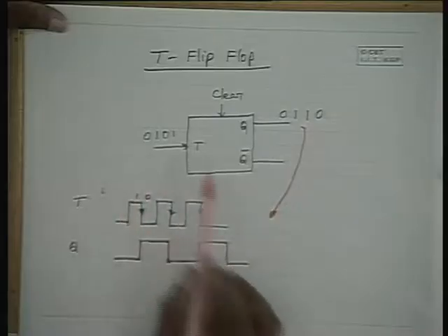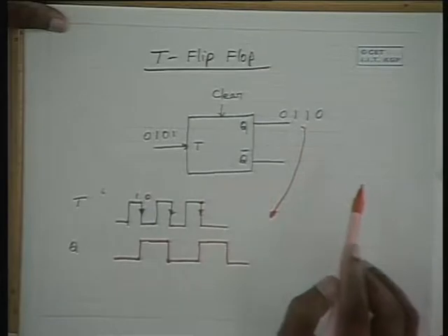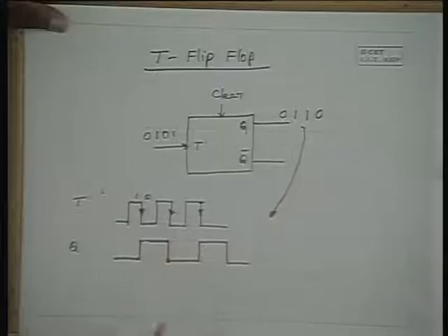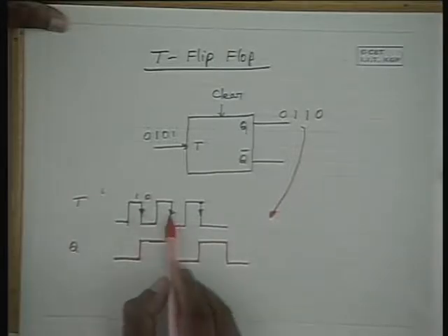It's a divide by 2 circuit. It can act as a dividing circuit for the frequency. If it is 1 kilohertz at its input, it will be 500 hertz at its output. That's because the toggling flip-flop responds only to the negative transitions.